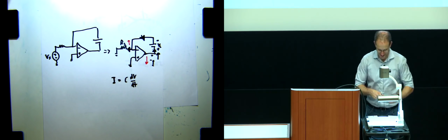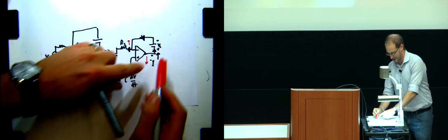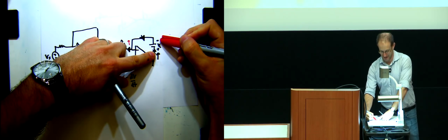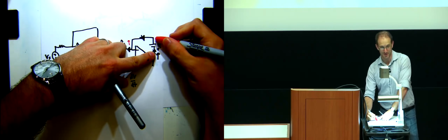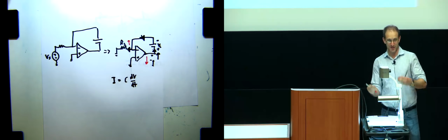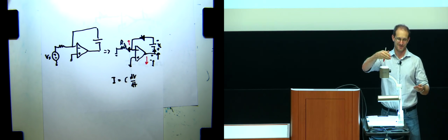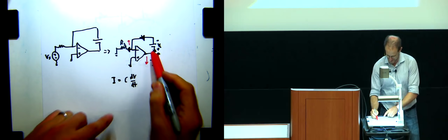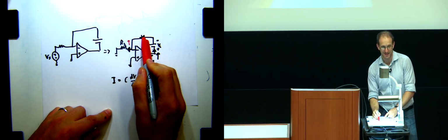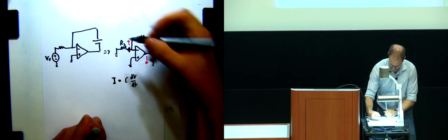This is where maybe the arrows may make it look a little bit confusing. Notice I defined the plus on the VC here and the minus there. That means this voltage defined this way is increasing. By passive sign convention, the arrow of the current has to be flowing into the plus. That current would be positive, and if I have an arrow going up here, it has to make a left turn there. Then at this quote-unquote junction, it has to be going down. So let me explicitly draw that.